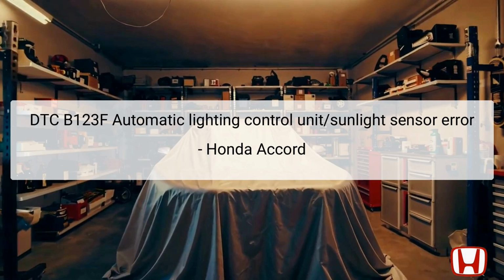The DTC B123F indicates an automatic lighting control unit or sunlight sensor error in the Honda Accord, specifically models from 2017 to 2023. This diagnostic trouble code is triggered when the vehicle system detects a malfunction within the automatic lighting control unit, which manages the vehicle's headlight functions based on available light conditions. The sunlight sensor, located on the dashboard near the windshield, plays a vital role in this process by measuring the intensity of sunlight, thus informing the automatic lighting system whether to activate or deactivate the headlights automatically.